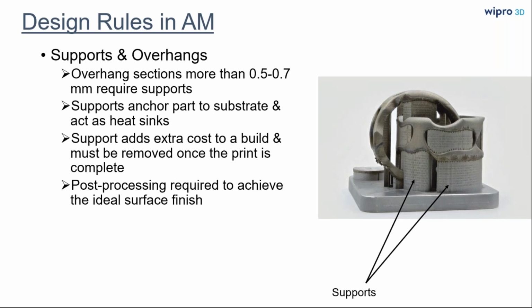And understandably, supports add extra cost to the build, and they must be removed once the print is complete, because they might hinder the part functionality. And often these supports are removed using some post-processing technologies, whether that's polishing, whether that's manually, whether that's machining.